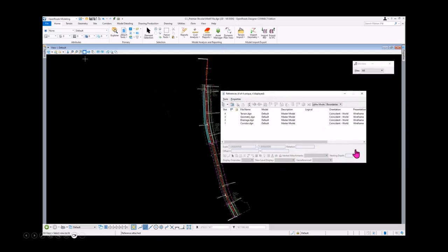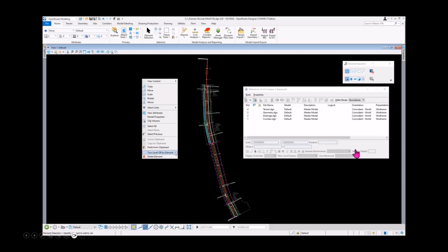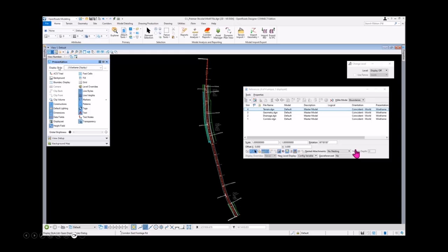Now that I have everything set up, I can do a fit view and create the name boundaries. I don't have to create the sheets in this same file. I can just create the clip boundaries. The reason for that is you can then share that potentially with other disciplines. So drainage, traffic, all could be using the same clip boundaries.